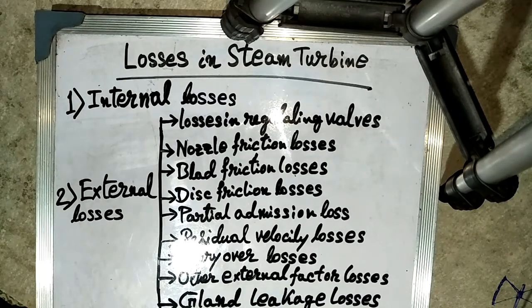Some portion of the kinetic energy of the incoming steam is spent in clearing away the steam existing within the blade passage, and this is called scavenging loss, which together with the friction losses is often referred to as the windage losses, in which some kinetic energy is imparted to the fluid at the expense of the kinetic energy of the blades.